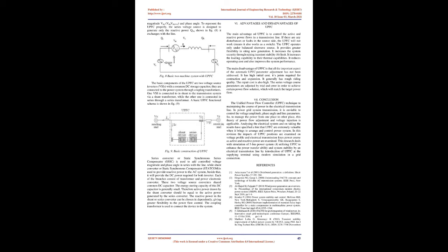Combined series-shunt controller. This is the combination of separate series and shunt controllers. These are controlled in a coordinated manner, or a unified power flow controller with shunt and series elements. Its principle states that the combined series and shunt controllers, shown in Fig. 6, inject current into the system with the shunt part of the controller and voltage in series in the line with the series part of the controller. Working principle of UPFC.